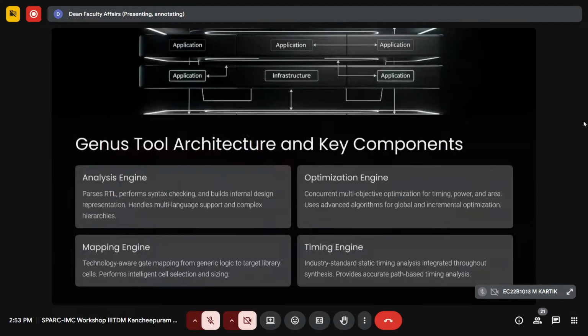Correct. So what will happen? Suppose you have a setup violation or a hold violation. What will happen? You can't determine. The flop will go to the metastable state. If the flop goes to a metastable state, then your functionality is crippled there. So the entire chip is gone, right?